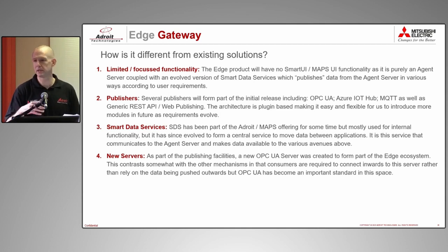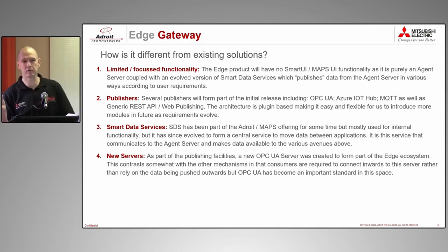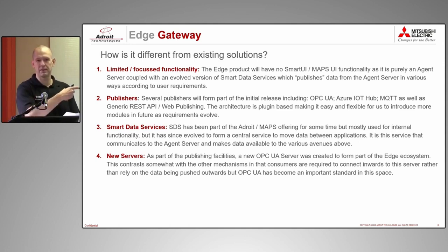OPC UA is a well-known standard, adhered to by many software packages, and a lot of other SCADAs in the world pretty much default or defer entirely to OPC UA as their input for data representation. As a weird convoluted spin-off, it actually allows Adroit Edge to act as an I/O server to other SCADAs. Just wrap your head around that. It's a bit weird, but it's true.